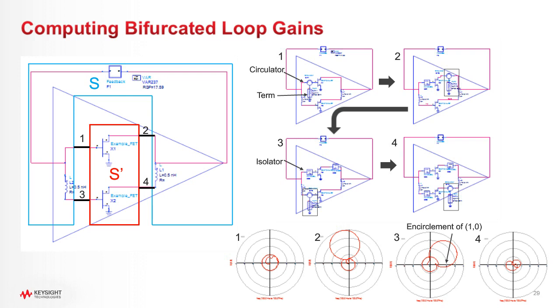And then there are 4 interconnects in this case. This is sort of an idealized case, but there are 4 different interconnects here. I basically create 4 different copies of the circuit, or I can run 4 different simulations too, that's fine. I start here, put a circulator with termination in here, inject the signal in, and observe the response at the other side of the circulator.